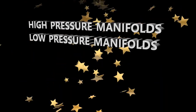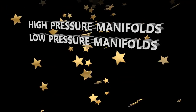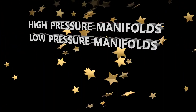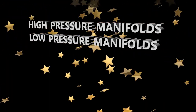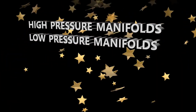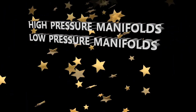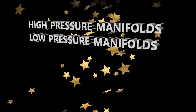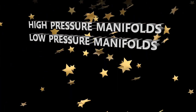Also, the clogging indicator is not going to operate if the temperature of the fluid is below freezing, so 0 degrees Celsius or 32 degrees Fahrenheit. You also have, which is typical of filters, the anti-spill device on the filter head, so it's pretty standard. And again, remember I said before about the bypass device, you also have that. So whatever the reason it's clogged, it's still going to allow that fluid to get back into the reservoir.